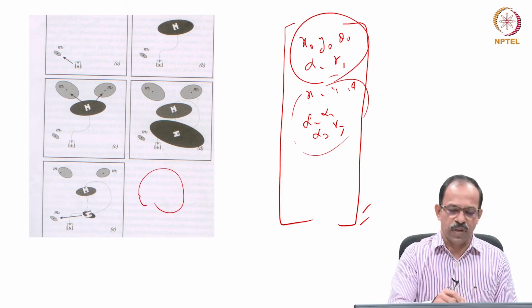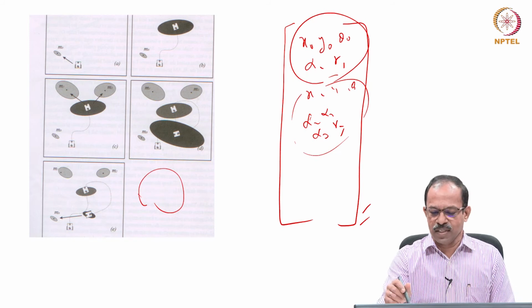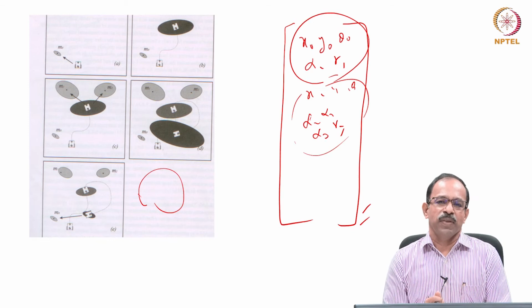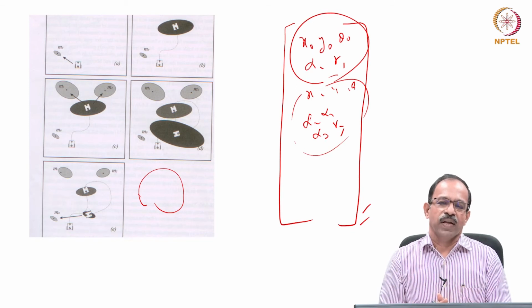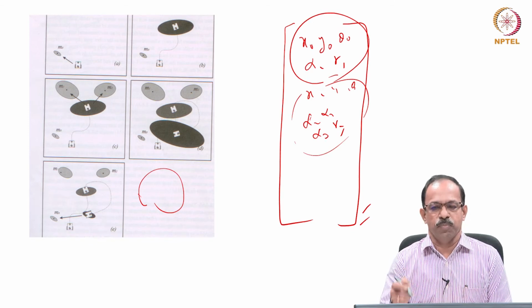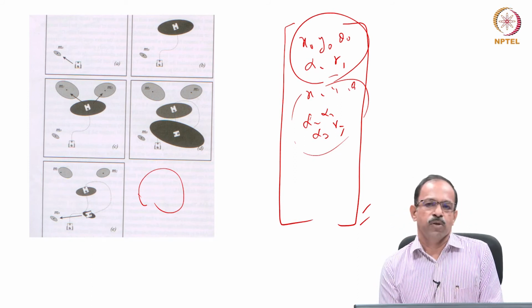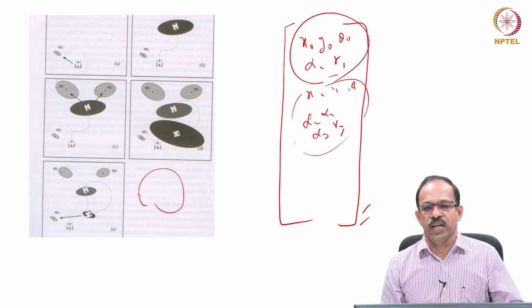This vector will keep on updating, and after many travels, as the robot keeps moving, at some stage you will see that no more updating happens. Then it says that, okay, that is the correct map of the environment and the correct position of the robot. This is the way the extended Kalman filter is used for localization and mapping.